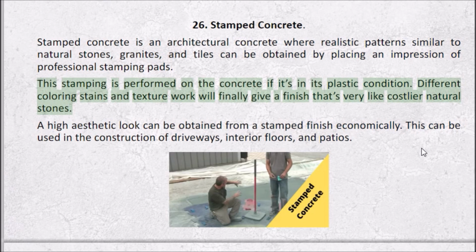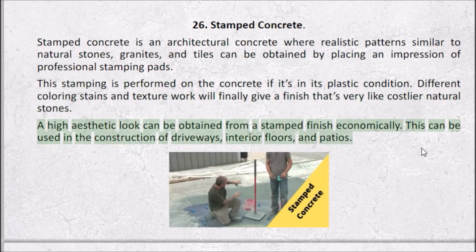Different coloring, stains and texture work will finally give a finish that's very like costlier natural stones. A high aesthetic look can be obtained from a stamped finish economically. This can be used in the construction of driveways, interior floors, and patios.